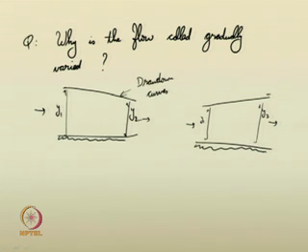If the water surface is increasing gradually as it flows from upstream to downstream, then the water surface curves are called backwater curves. One can easily understand the meaning of these terms, so we are not going to discuss the language of these terminologies further.